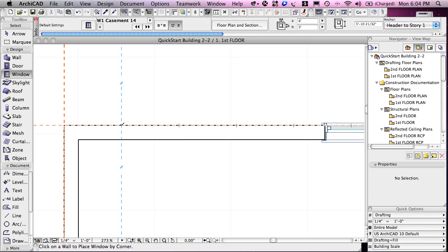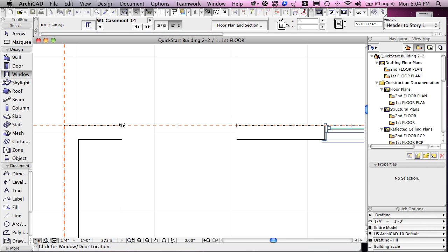So here we have, now I'll click, and you remember that cursor that was the double eyeball. You can see the opening in the wall to the right or to the left, depending upon where I move my mouse. I'm not clicking yet, I'm just gesturing. Now when I click, it determines that that's where the opening is. And remember that there's a status bar down here that gives me a clue. Earlier it said click for the window opening. Now it says the orientation. So I'll say the window is oriented or facing out here.